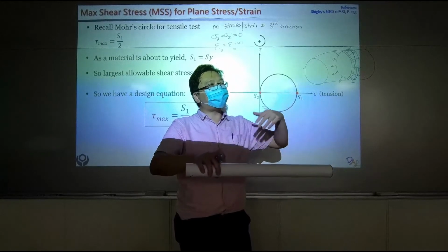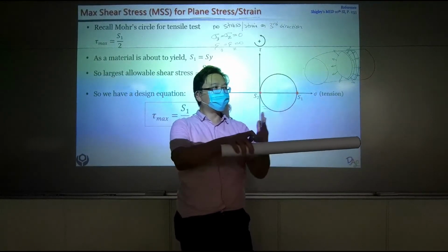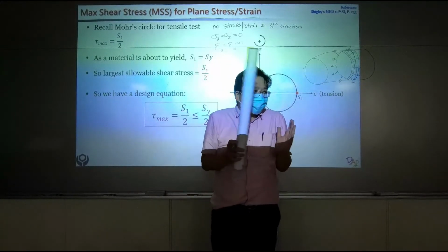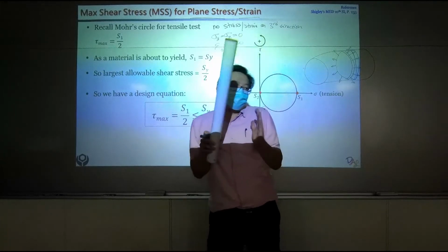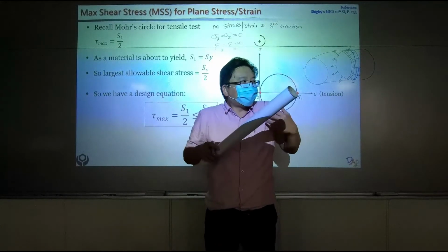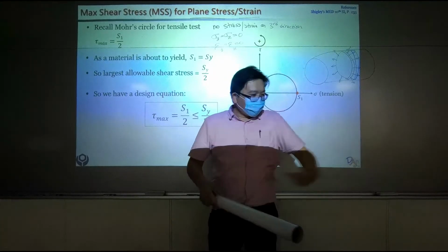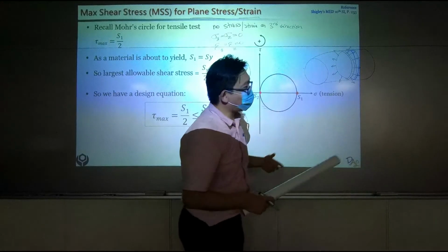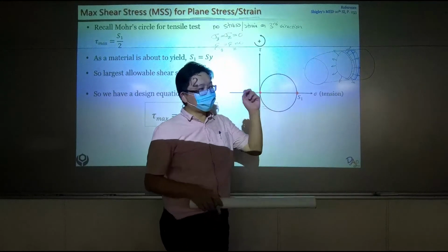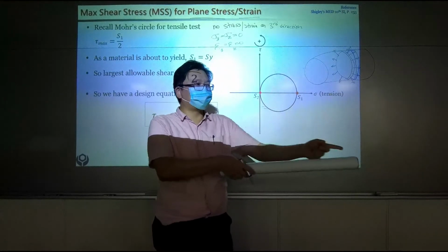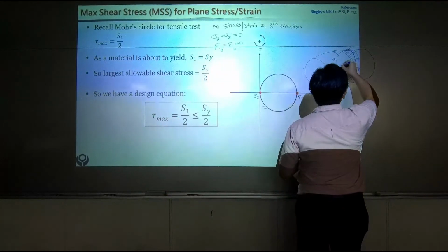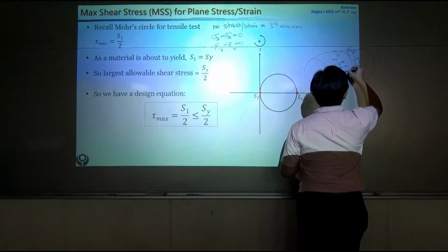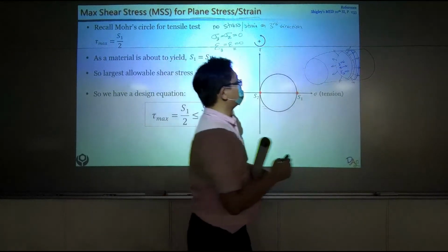There cannot be deformation along this direction. I'm pushing you, you're pushing me. Because we're all squeezed in this huge material, we cannot deform in this way. Since we cannot deform along this direction, we have no deformation, no strain. So people call this kind of problem a plane strain problem because the strain along this direction is zero. So here, if this is the third direction, strain third is zero. They call this a plane strain problem.